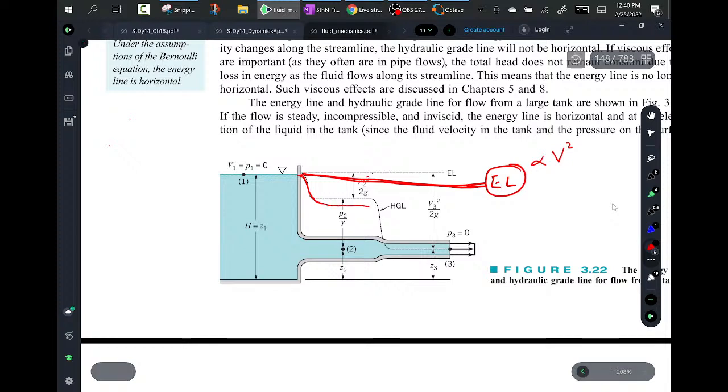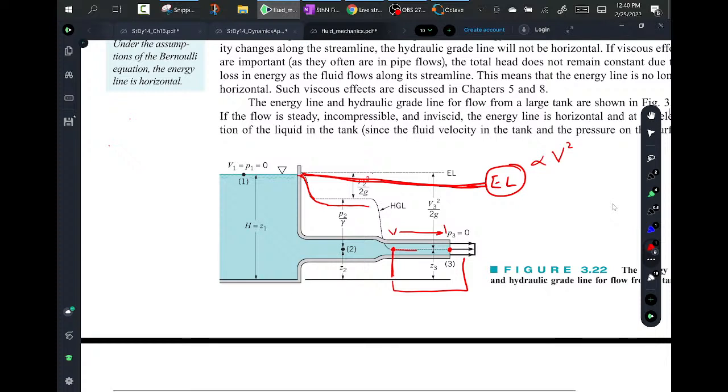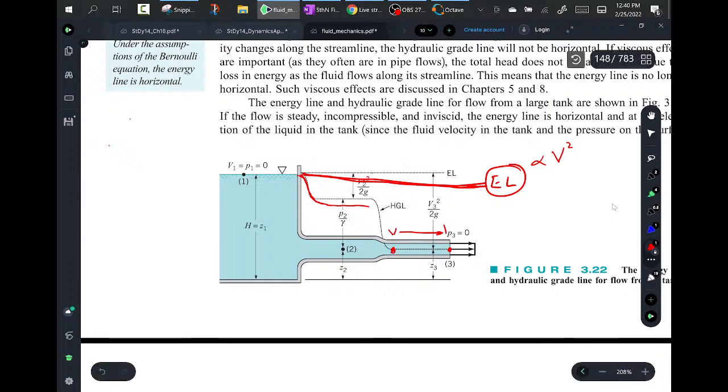And so this last section, for example, let's just consider this. Think about this. Bernoulli's equation back at this point would tell you the pressure here has got to equal the pressure here, because the velocity at this point is the same all the way down this tube. And guess what? The elevation's the same. So wait a minute. What's going on here? So the velocity is the same. Let me just address this part of the pipe.